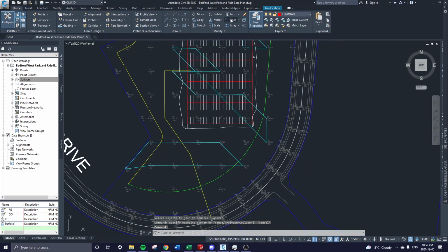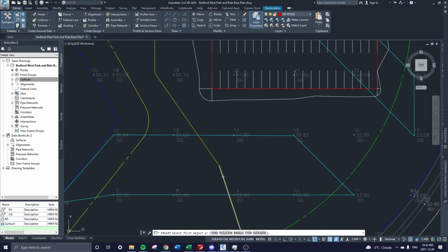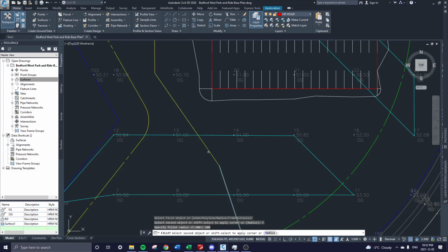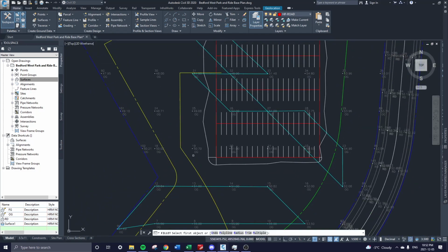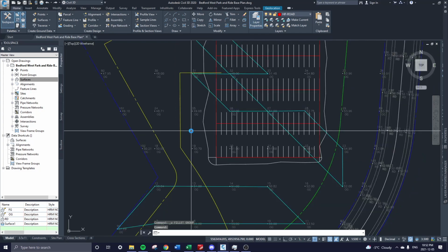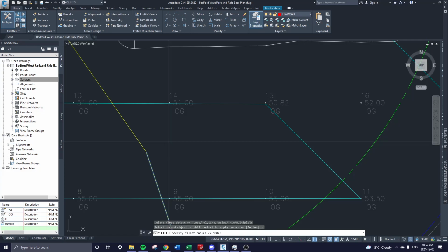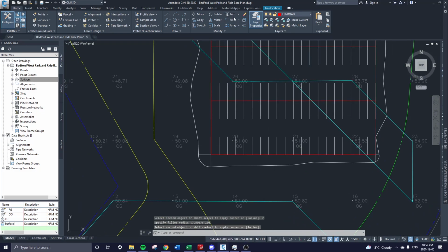Terrific. And let's chuck some bends in. So I want to make centerline turning radii. Let's say a turning radius of 200 meters. You see how that puts a nice little curve in there? Okay, awesome. That tangent's significantly shorter. Okay, well then maybe I'll reduce that radius to say 100 meters. 100. Click on your next. Awesome. Okay, and repeat.